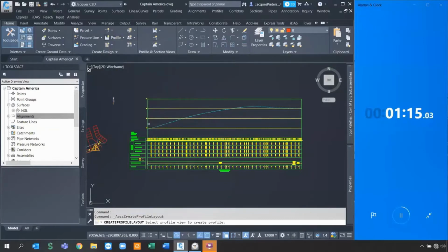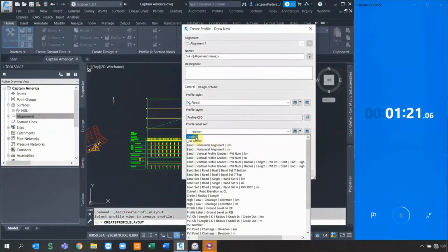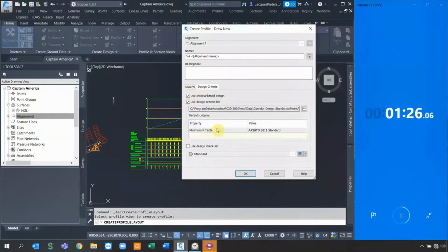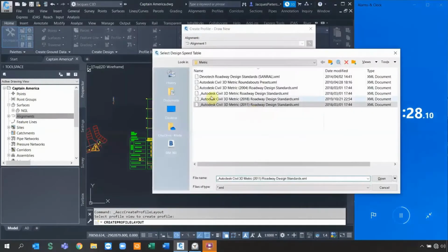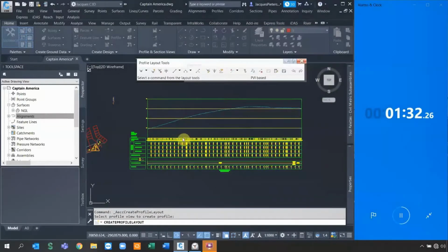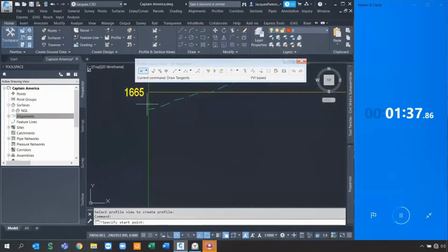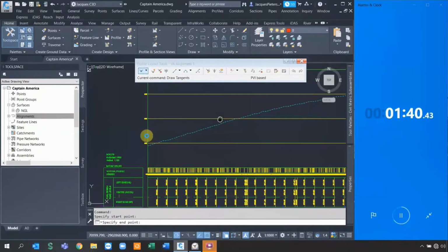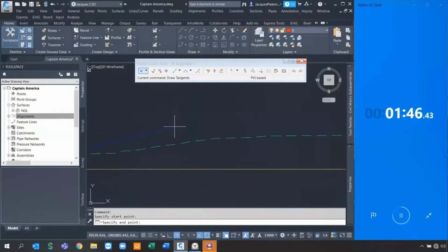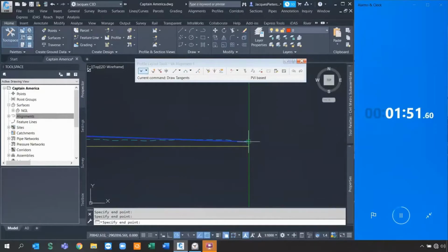The next design is the profile design itself. So how I'm designing it as a civil engineer, I just set up one setting. I don't want labels on these, and it also has its design criteria, which is normally our K values that we need to specify in a long section. So I can say use design check, and there we go. I can just quickly model up and design this road. Just for time-saving purposes, I'm not going to design it 100%, but I'm going to at least design it very close to accurate. So let's say, for example, I'm going to place it somewhere over here and just snap to the end.